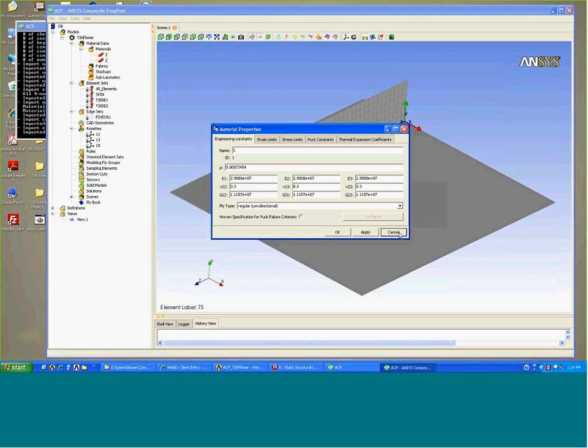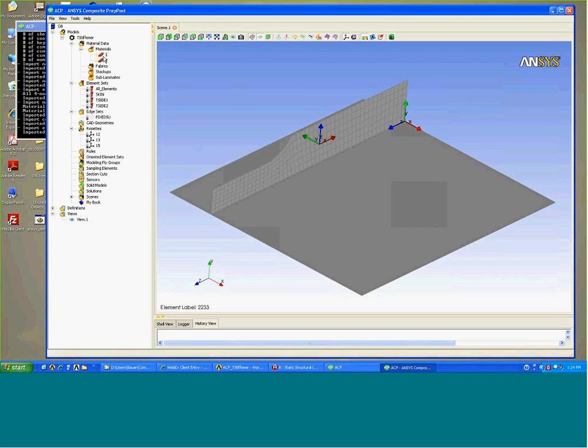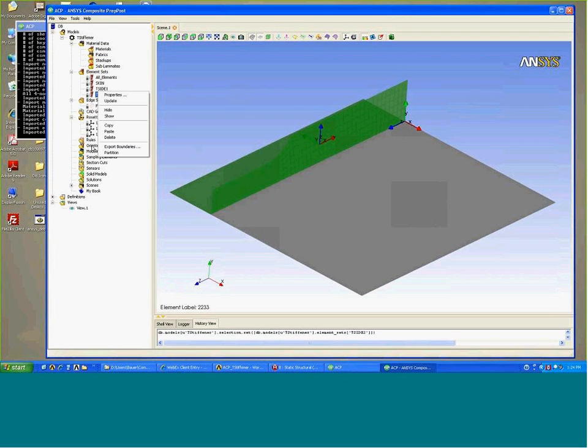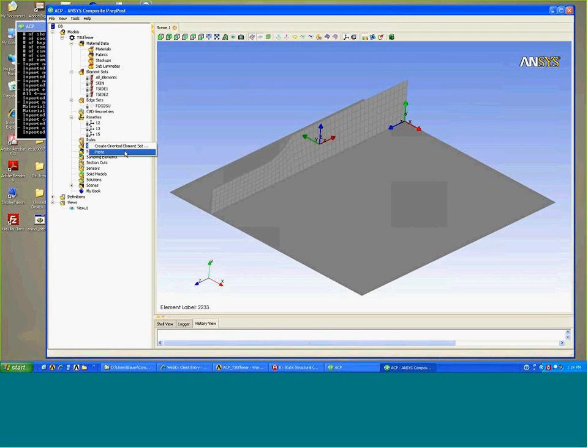They are an example homogeneous material, and we won't need these for this particular problem, so I'm going to go ahead and delete these. If you right-click over each item in the outline tree, you have the ability to create materials. Essentially, right-clicking over various options in the outline tree gives you the different operations you can perform with that specific item.